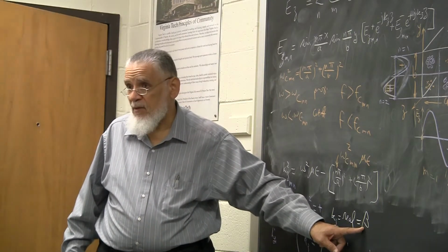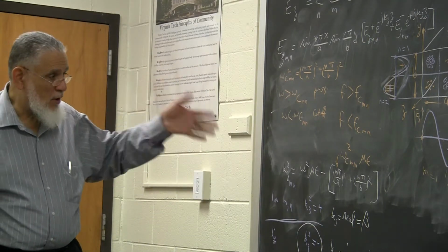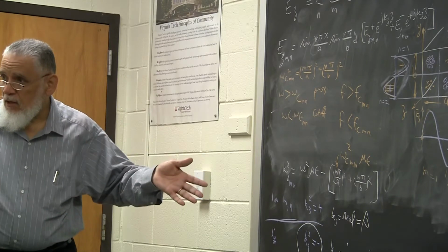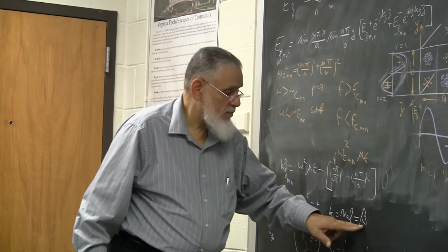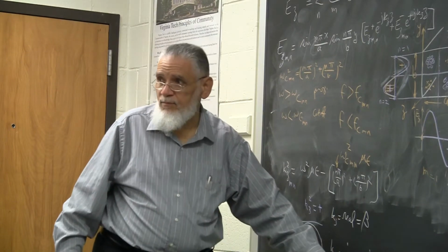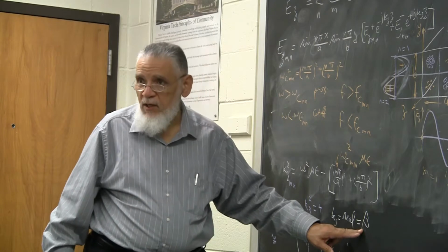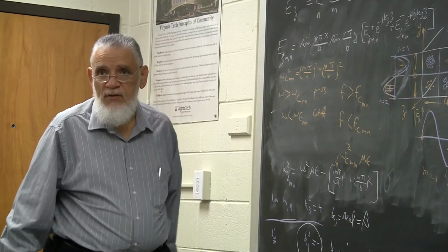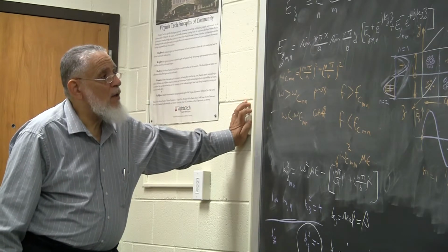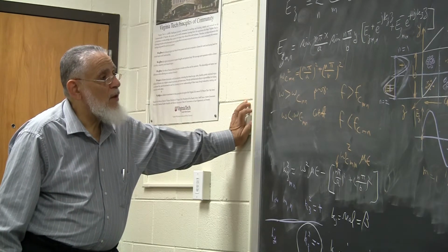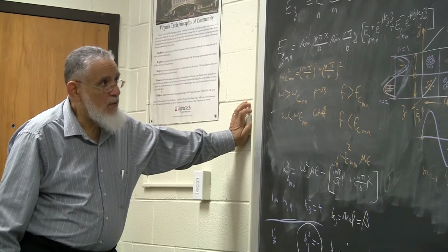So you'll have a gamma. But if you work with ideal dielectric and ideal conductor, there's no alpha in the gamma, it's only beta. But it's not this alpha, it's alpha in the cutoff. There will be alpha in the propagation, which is going to be a tiny loss coefficient to accommodate for the imperfection in the conductor and dielectric performance.